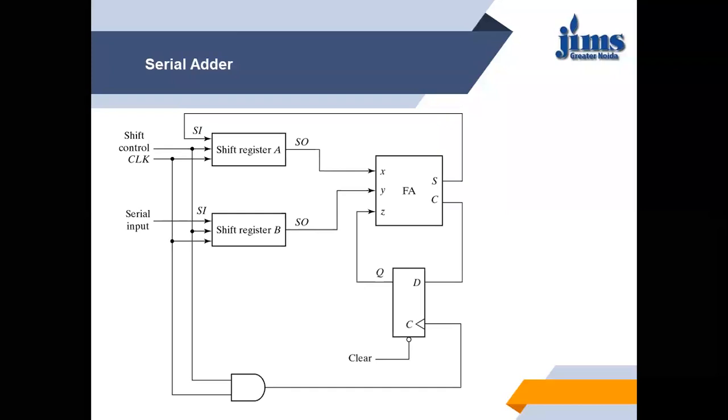Now another solution, when you are not bothered about the time, but you are interested in saving money, then we use a serial adder as compared to the parallel adder, because the hardware requirement of the serial adder is very less as compared to the parallel adder. So here we can see the block diagram of the serial adder.